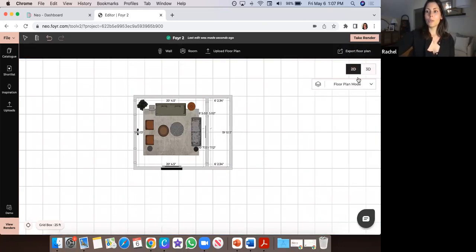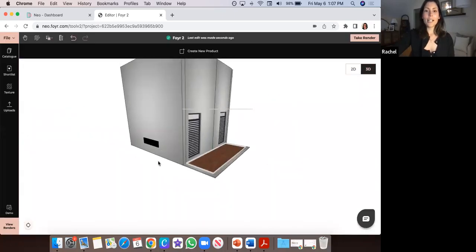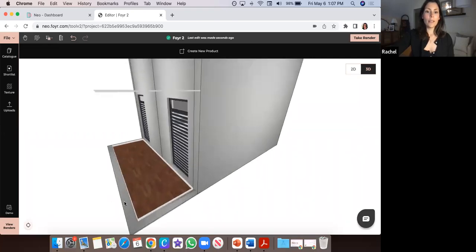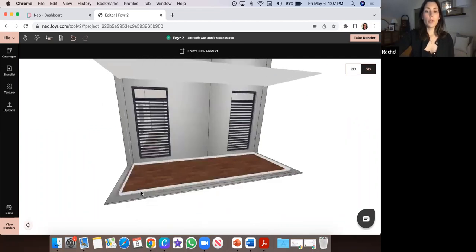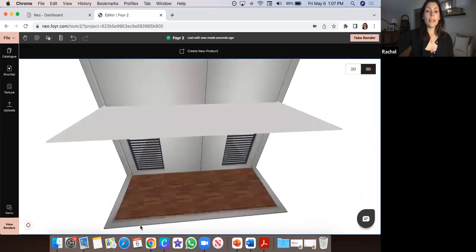Coming back to where we ended there, we're in 3D mode, and these 3 walls are down at ground level. If they're too thick, you can change the thickness in 2D mode as well. I'll show you that. You can click on this auto baseboard and delete it away. You can drag and drop an outdoor porch texture, whether it be wood or stone, whatever it may be. I'll show you how to do that next. Great question.